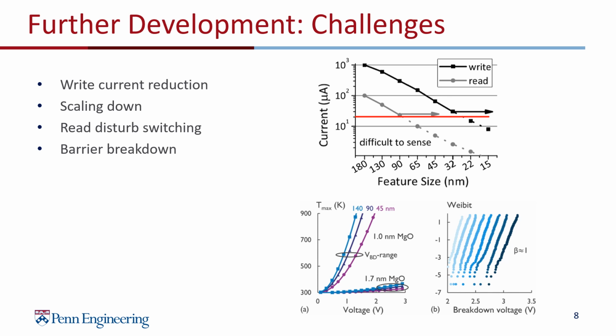In terms of the development of STT-MRAM, the future is very bright, but some challenges must be addressed before STT-MRAM can be heavily relied on. The first issue is reducing the write current, which is less than that of MRAM, but still should be reduced to further decrease power consumption. In the graph on the right, the future projections of the current as devices are scaled down can be seen. The graph shows some uncertainty, but ideally the currents can continue to decrease as devices are scaled down.